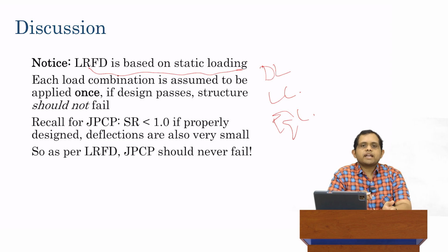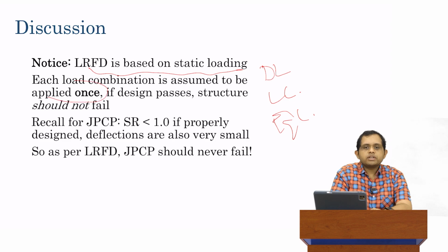For each of the loads, we calculate stresses. If the stresses caused by the factored loads are less than the factored resistance, which is some factor of safety times the strength, then we say that the design is successful or the design has passed. But note, the load is assumed to be applied only once.